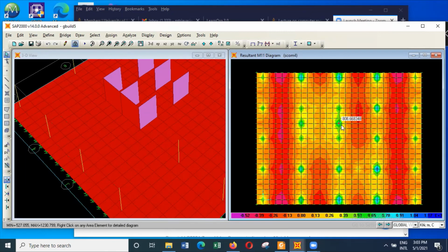And when you reduce the thickness of the raft, you might run into some problems with shear. And if you have any problem with shear locally, then in that region, you can provide vertical links within the raft, and these vertical links can actually play a dual role. During the construction, these vertical links can be used to support the top mat of reinforcement in the raft. So having some shear reinforcement at local pockets is not a major problem, and you can actually have